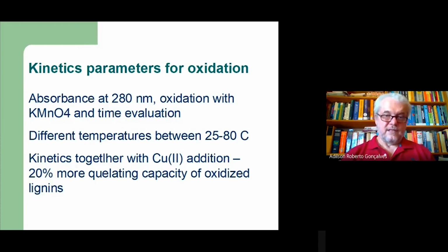The first result here is that with the kinetics together with copper addition, we can see a higher chelating capacity of this oxidized lignin, with about 20% more metals removed. Remember that this chelation is used here as a parameter, but the material can be used even for agrochemical delivery or for wastewater treatment for the removal of some metals.